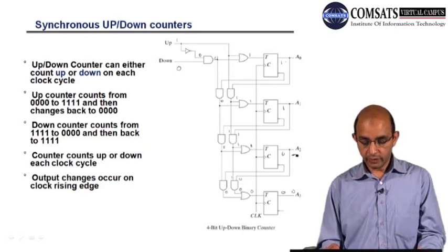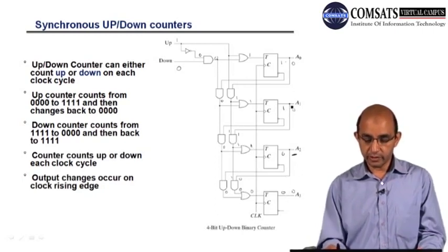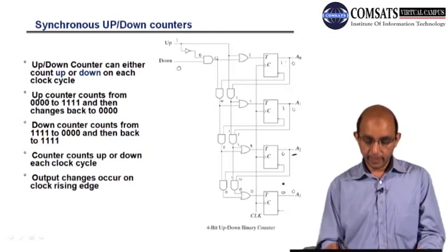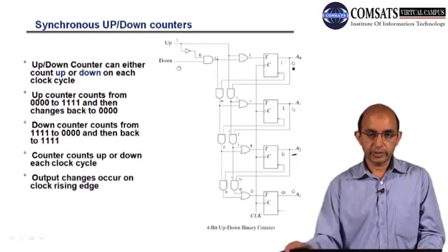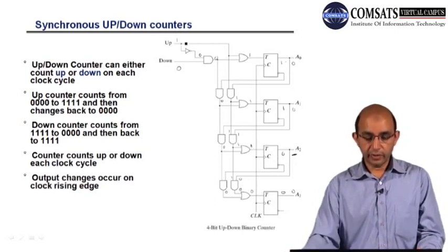So I'm writing like this, in this direction. This is 0 and this is 0. If this is the most significant bit and this is the least significant bit, then before we had 3, and on the next clock that 3 will be 4. Now we have 4: 0, 1, 0, 0. So this is when we have count up high and count down at 0.